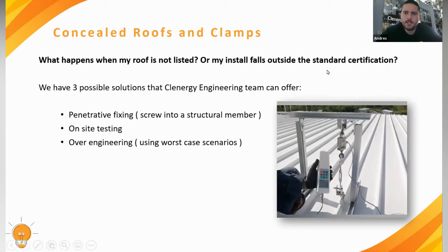The on-site testing is shown in the picture on this slide, where basically a frame is set up on top of the roof sheet with the interface clicked on the clip lock roof. It then applies a certain uplift pressure until it detaches, and that's how we calculate the maximum capacity of the roof sheet.